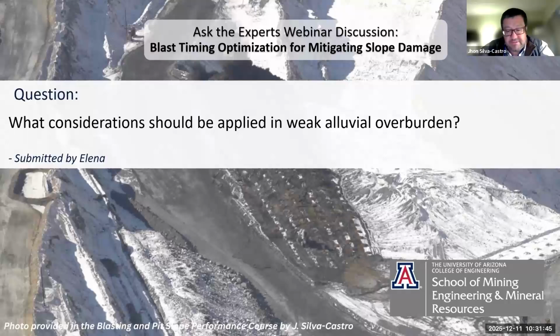Yeah, one thing is related and not related specifically to this weak alluvial material. Sometimes you have to think, the first question, what Pat was saying, is: do I need explosives? This is the first question. Sometimes you also need to see how fractured your rock mass is. Do you need explosives to actually create fractures and fragmentation, or do you just need to move the material? So those are the things you need to take into account at the beginning. Yeah, great point.